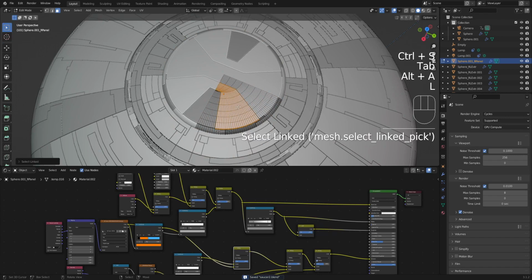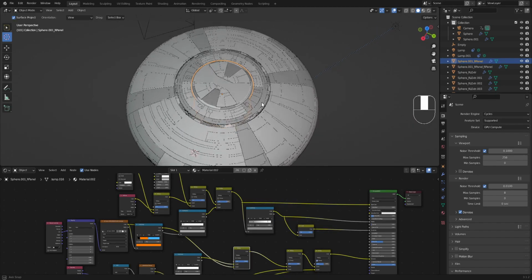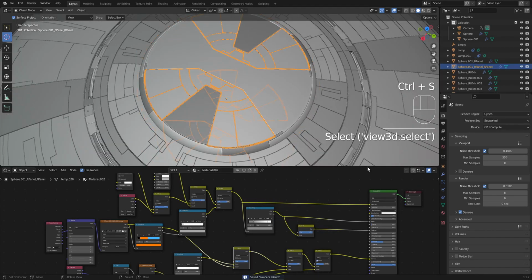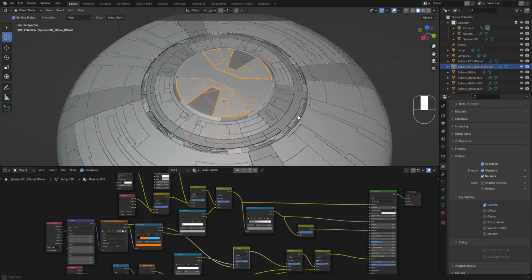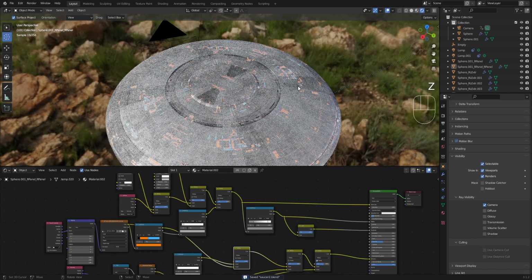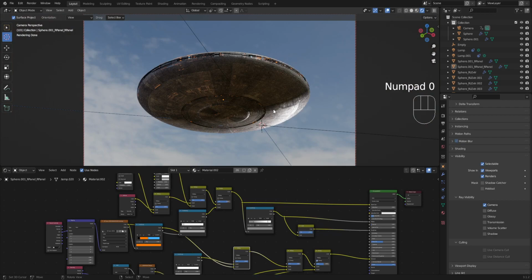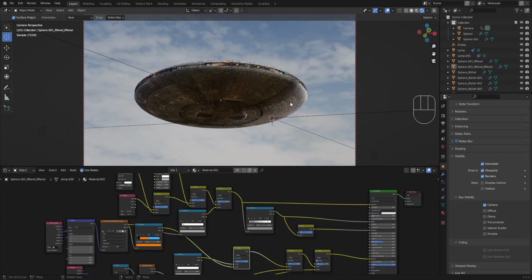Okay, and here, just this part, you can actually bake this to normal if you're good at making cages on your model. So object properties, turn off everything except the camera. So it won't contribute on the diffuse, glossy, transmission, volume scatter, and shadow rays. There you can see the cut lines just subtly reflecting the lights. There we go.